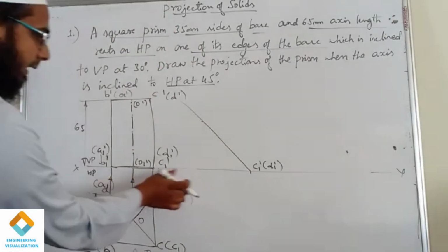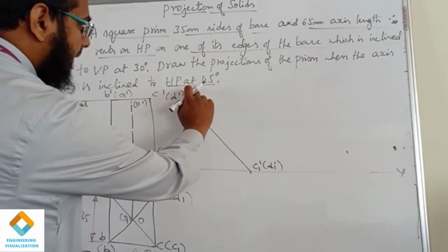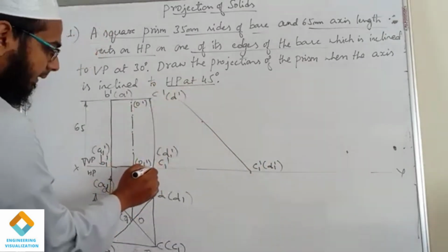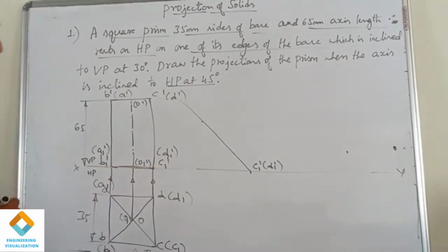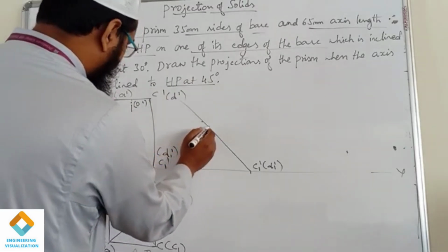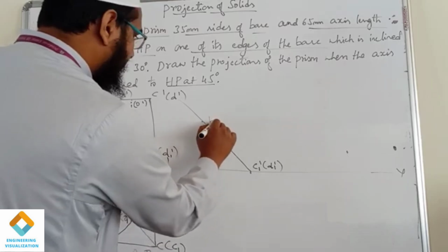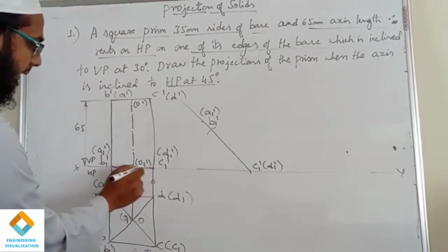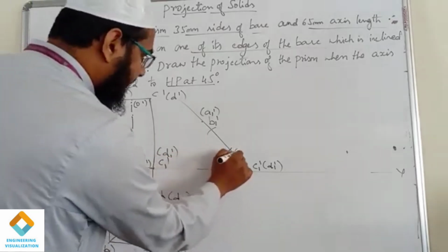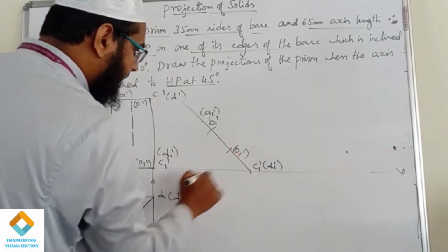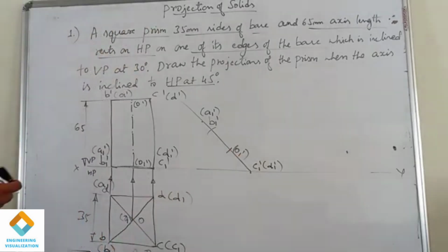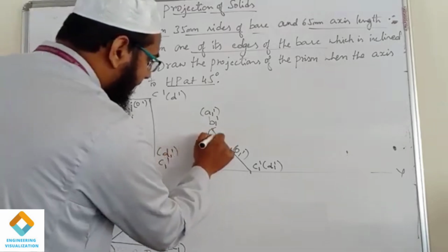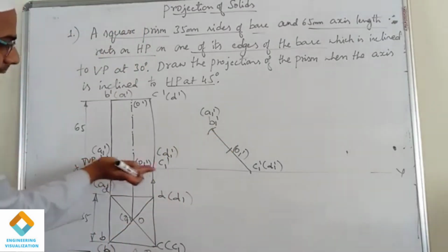After taking the reference point, keeping the protractor, marking 45 degrees and drawing an angle line, next take the compass and, measuring from C1 dash to B1 dash, cut an arc. This is B1 dash. The second arc you cut from C1 dash to O1 dash. This is O1 dash. After cutting these arcs, this is the length we require. So we have drawn the bottom part.